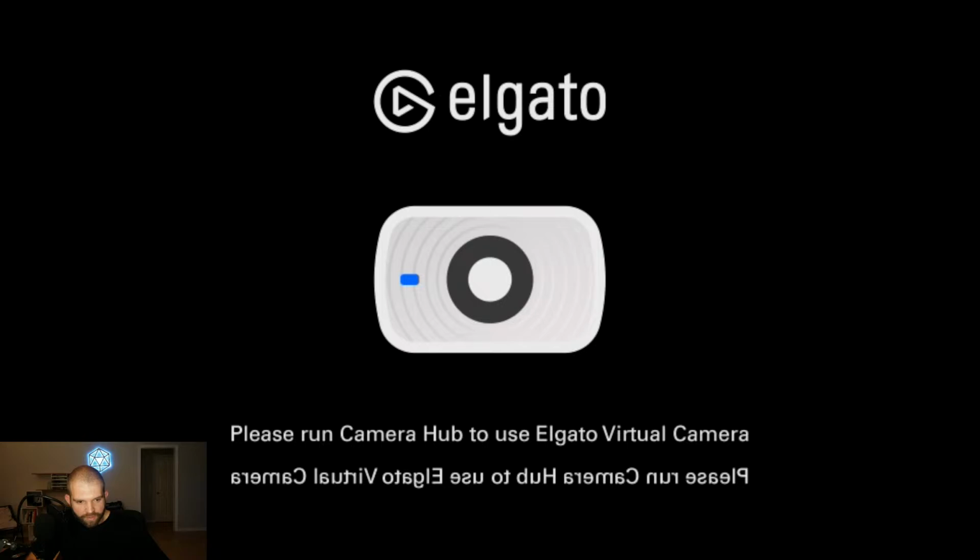I'll add another face or another surface sort of as a base mesh underneath and select that as part of the AI image generation as well, so that I have sort of a backplate that'll catch some other textures. So I'll select this whole array of geometries and the bottom plate, hit tab, select all these top faces for the last time, as well as the bottom face right under this array. There we go. Project dream texture.